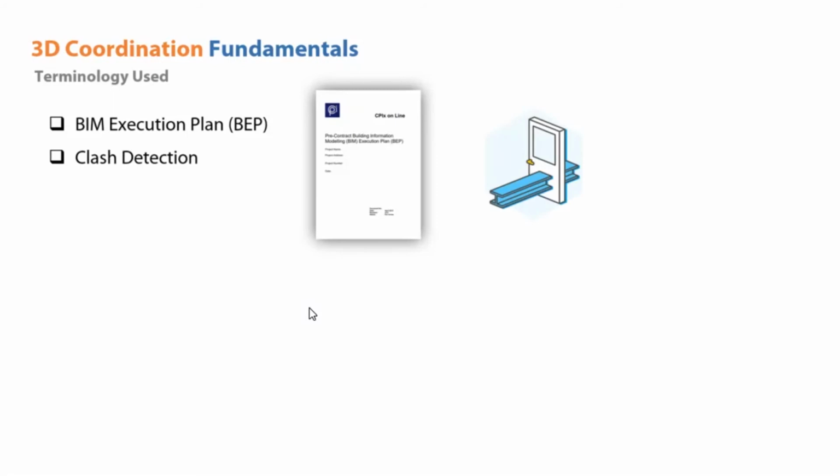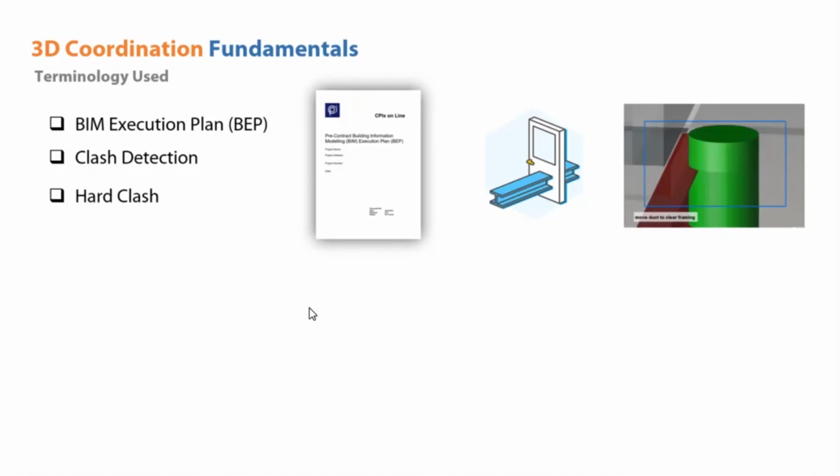Clash detection is a process that allows for effective identification, inspection, and reporting of interferences in a 3D project model. Tools such as Navisworks' Clash Detective tool or even the BIM 360 model coordination module can help a user to reduce the risk of human error during the model inspections. It can also be used as a quality assurance check for both completed design work and ongoing audit checks of the project's progress. A clash is considered a hard clash when model elements intersect with other models' elements. For example, when ductwork is passing through a solid beam, this is considered a hard clash.